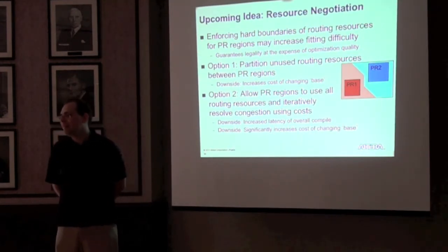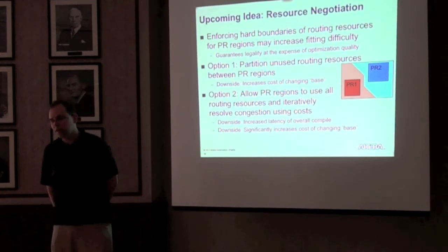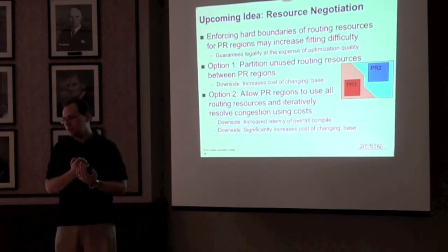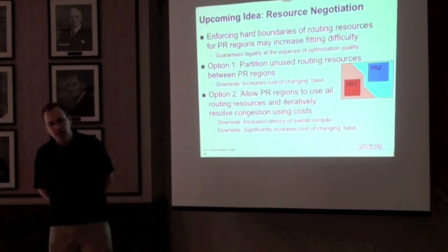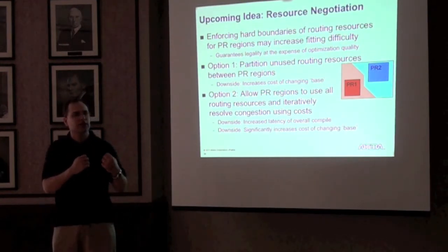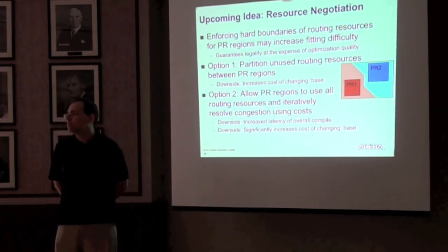That might be possible. Well, I have actually a second question. It seems to me that the initial floor planning is very important because it seems to dictate a lot of performance later on. Is it true that your current user interface is running a view-based approach? Is there any programmatic support, like a particular script that the user could create their own floor plan with? Yes. So all of our commands, right? There's a Tcl package for partial reconfiguration and pretty much any incremental compilation. All of what I described here about setting up the project and compiling the project and the different revisions can be completely programmatic. But is it documented? It will be.